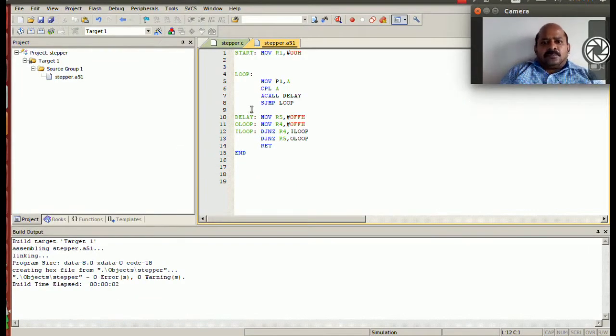Okay, let us extend this program to generate a sinusoidal waveform. Before you write the program, for generating a sinusoidal waveform, we need to work with sampling concepts. Because a sinusoidal waveform is not a linear waveform, we need to get some samples of the sinusoidal, and we have to keep on dumping the samples, or the amplitude of this sinusoidal wave, and we have to plot the sinusoidal with respect to the time.